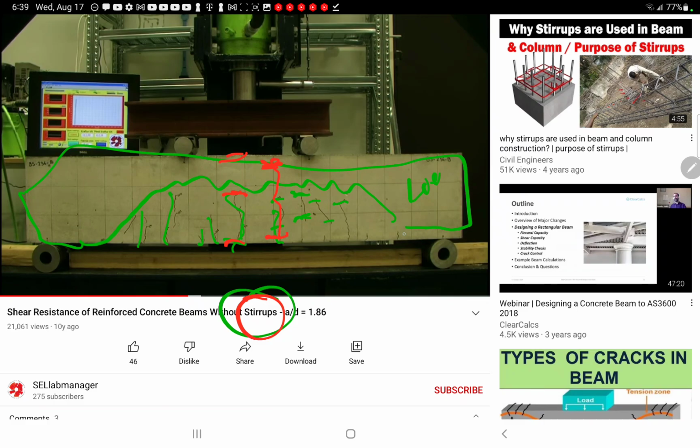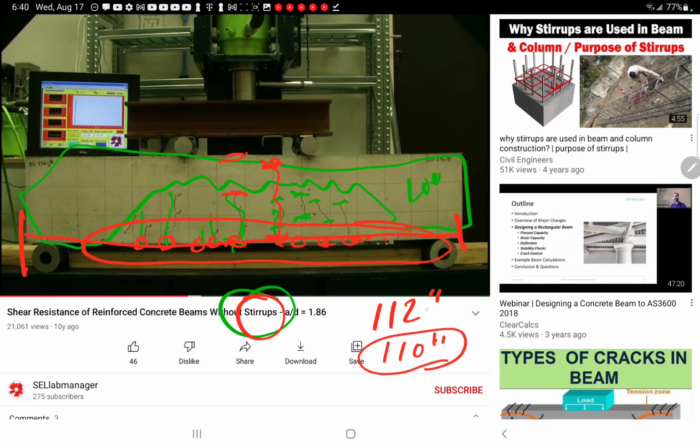And in the bottom part of this section, it's going to be a much deeper video dive for you. I don't know when I'm going to get to that. But this is now the steel being stretched. And you see all the opening. You add all that up and you can determine what's going on here. You could also measure from here to here and say you have 112 exact inches. But when you started off, you had 110 exact inches when it was flat. So you can see your rotation is taking up 2 inches.